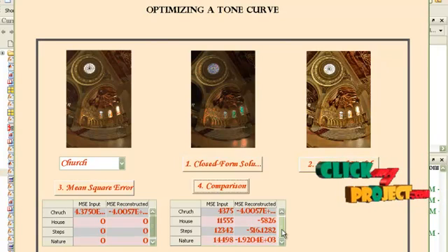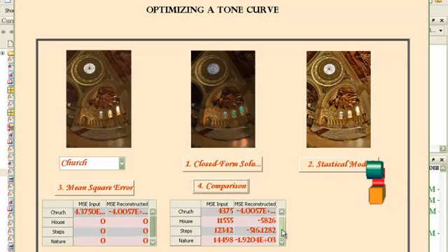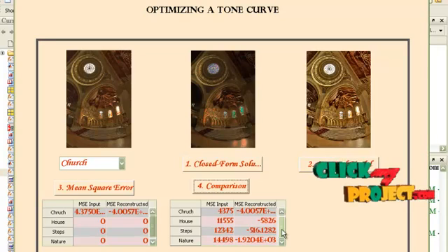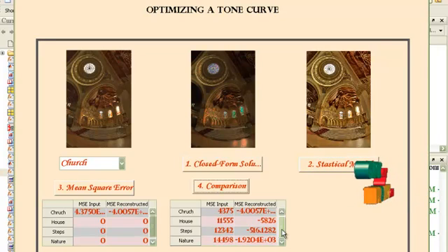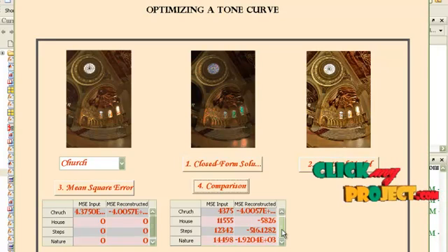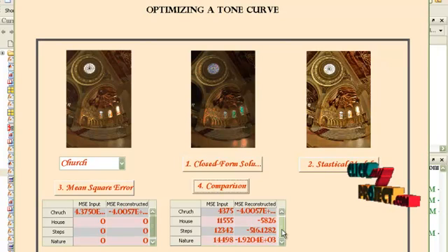Finally, we are able to understand that these distortions provide a very good analysis on the MSE. Our proposed tone mapping methods can directly improve the compression efficiency by using bit depth scalable video coding. The proposed methods are designed to produce a better reconstructed HDR representation. A direct consequence of this design objective is a reduction in size of the higher bit depth layer, which contains the difference between the reconstructed HDR image and the original one. Thus, our method can lower the total bit rate of the bit depth scalable coding.